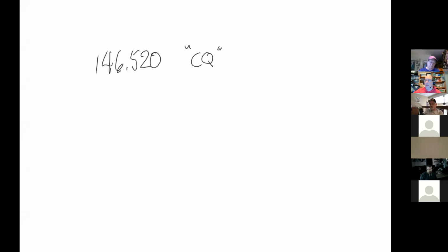If you're on 146.52, what do we call that again, everybody? What's that frequency called? Universal. That's the national simplex calling frequency. Because it's simplex, there's no repeater there. We do use CQ on that frequency. You can call CQ on 146.52, N7JI. Now, I might also say November 7 Juliet India. That would be called phonetics. The reason I use phonetics is because they eliminate some of the ambiguity of letters, because C, Z, G, and D all sound the same in bad conditions.